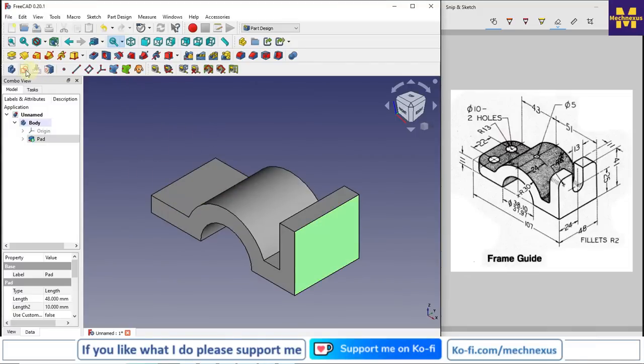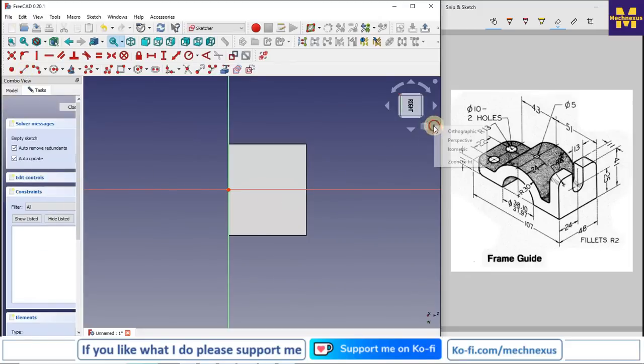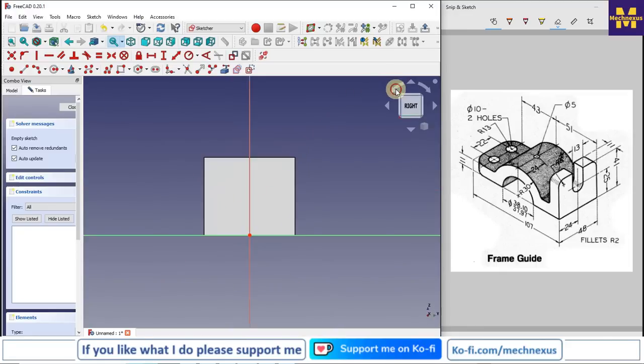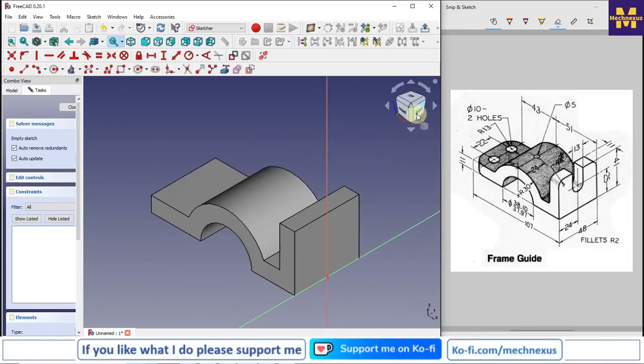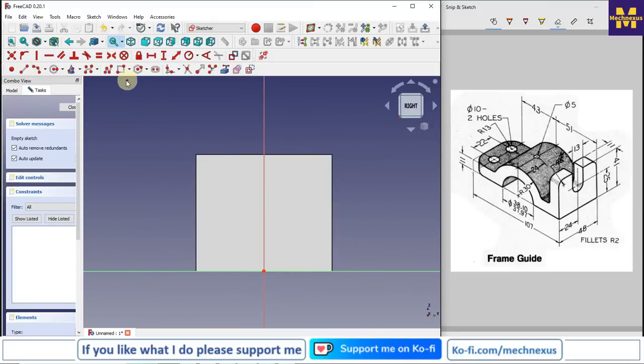So I will select this face and I will say sketch. So here I will rotate my model, I will say yes, and now I will convert my top edge here, and then I will draw a rectangle here, and I will make it symmetric with this and my axis, and I will delete this line and I will say 3-point arc, and I will make it tangent,